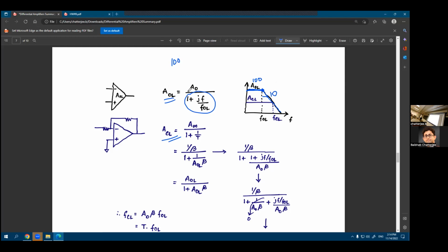What is the representation of something being 10 times smaller in dB scale? It's 20 dB, right? So that's why, if your quantity is voltage gain, remember, this is not power gain, the definition of dB is basically 20 log base 10 of a ratio, right?